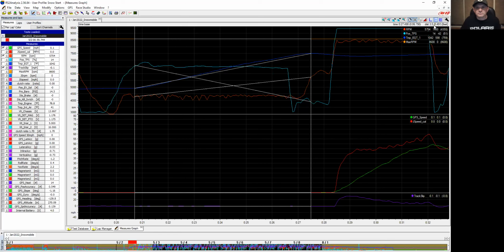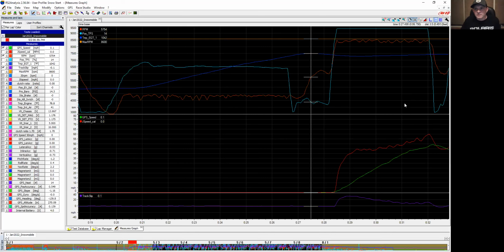The sled didn't move hardly at all because they were in time mode here, so the sled isn't moving. But the other interesting thing is that EGT grew from what we started at to where we ended. It grew 759 degrees over that time frame. So it's just information that, if this is important to you as users, and this is something you want to track and try something different the next time the rider goes up there, try to get them to do it longer, whatever, you've got some information to track what the result is. Okay, and then I'll turn that back off so we can get away from it.